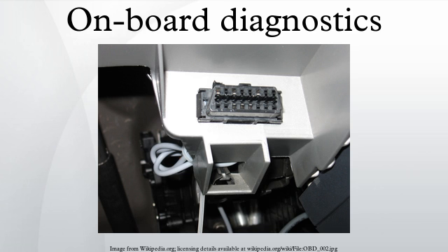OBDI was largely unsuccessful, as the means of reporting emission-specific diagnostic information was not standardized. Technical difficulties with obtaining standardized and reliable emissions information from all vehicles led to an inability to implement the annual testing program effectively. The diagnostic trouble codes of OBDI vehicles can usually be found without an expensive scan tool.